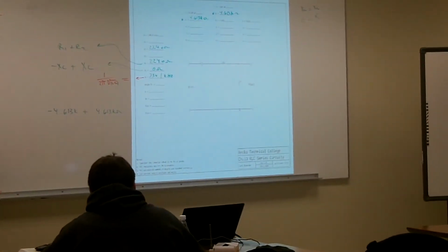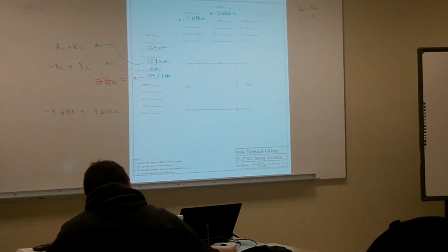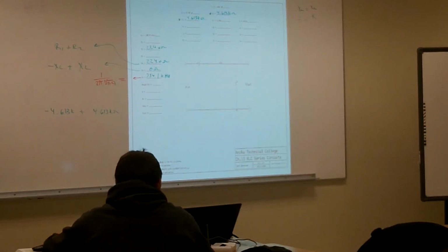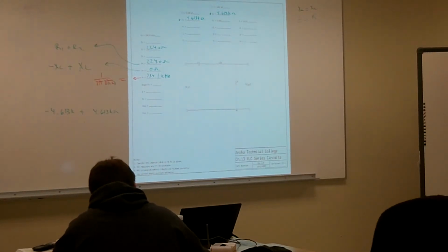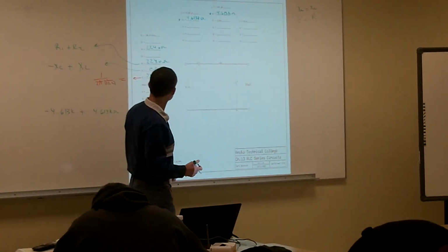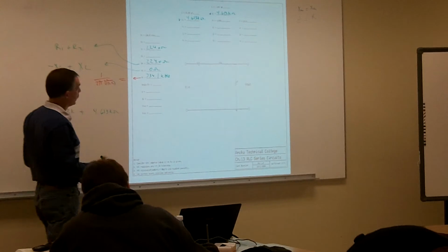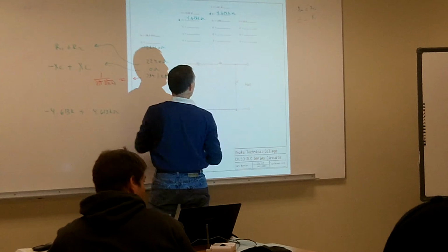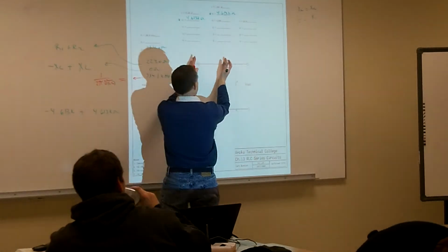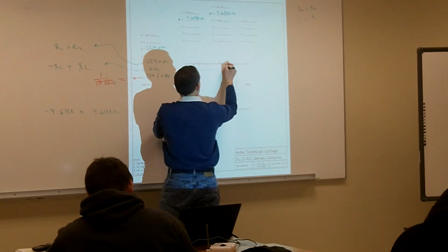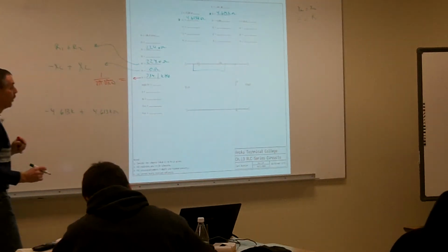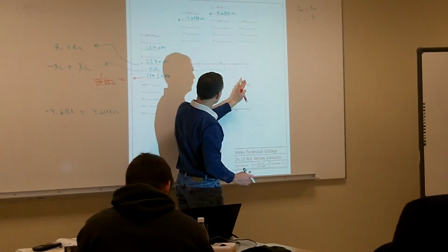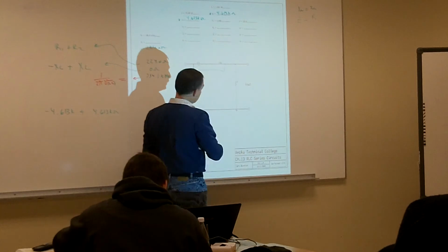Because right at this point, X of L and X of C are going to cancel each other out, and I don't have any reactance in my circuit. Those two are just canceling each other out, and so that makes it a purely resistive circuit. Those two are just ignored. The total reactance between these two is 0 ohms. It's basically like a short when I'm going across both of them. So the only thing I have left in my circuit is the resistance of my resistor and a little bit of the resistance of my windings.